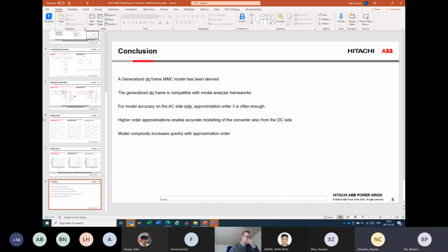But it also depends, Matt. When you talk about the grid as DQ single, it also depends on how your grid is. I mean, is it perfectly balanced? Feeders are all symmetrical, transposition. I mean, there is always some element of assumptions. Yeah. Actually, I should have mentioned that when we had the previous section there. When you use the DQ transform, we always assume we have a symmetrical system in the stationary frame.